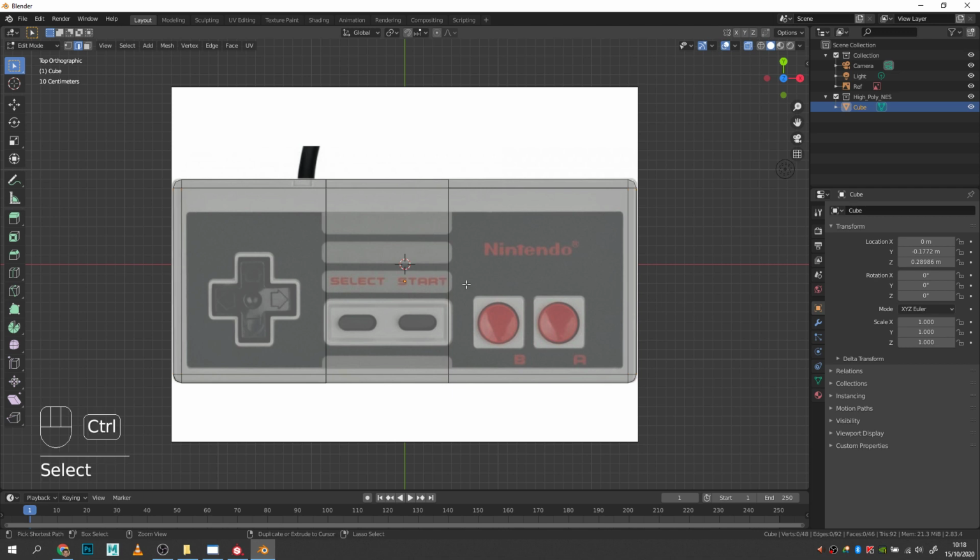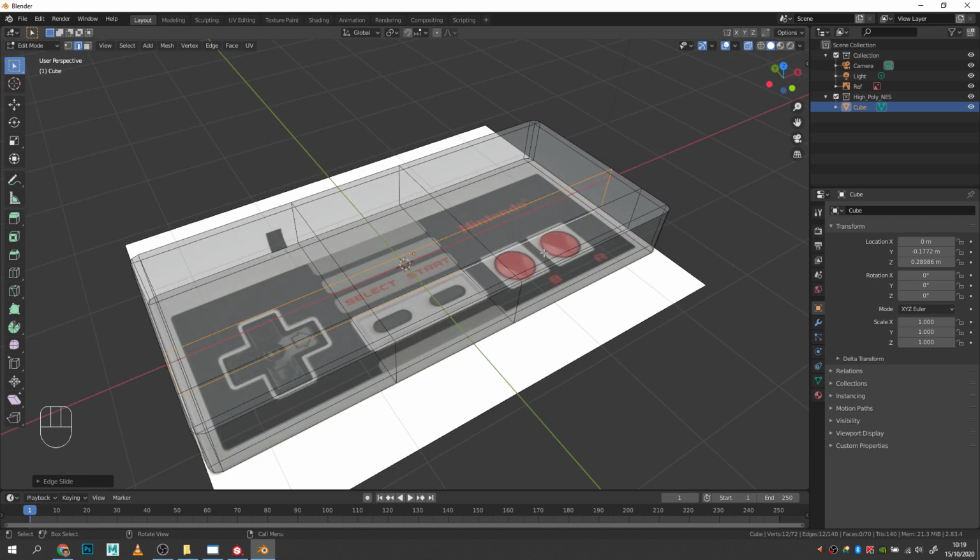Sorry, I'm not going to do that. I'm going to go Control and R to put 1 in. Again, I'm going to scroll wheel up to make sure I create 2. And I'm going to move the first one into position. It's the bottom one. And then I'm going to Alt click the top one, GG, and bring that one down into position. Cool. And then we've got an area here where we can cut out at the bottom.